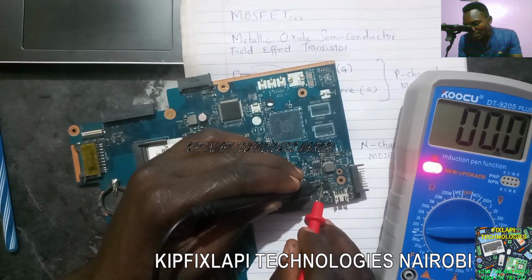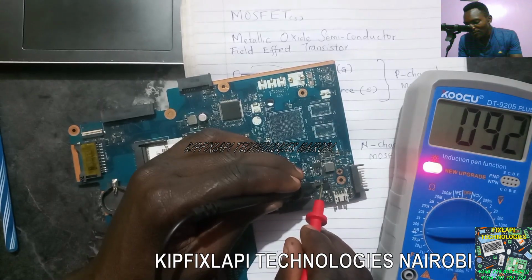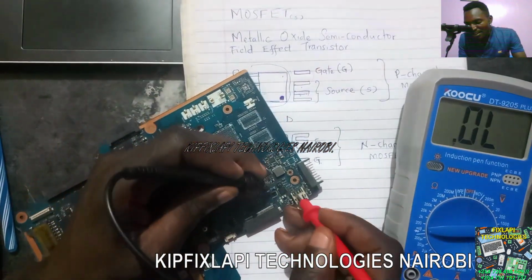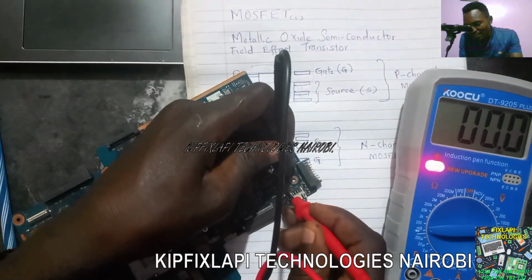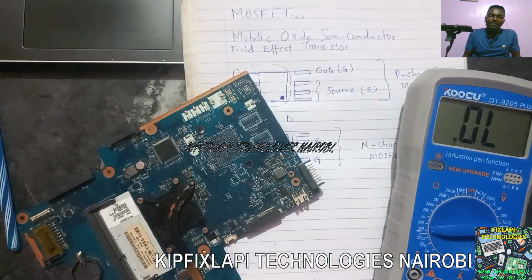Still connected, because that's pin number 3. What about number 4? No beeping, right? And no continuity. So the fourth pin is not connected to it. First three, 1, 2, 3. What about the other pins? At this particular side, you have this far end pin. You can hear. Yes. So these four pins are connected together.